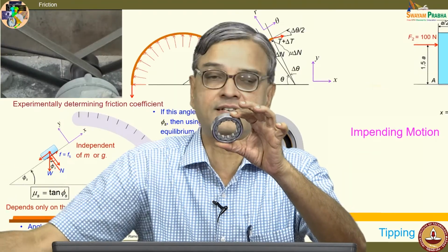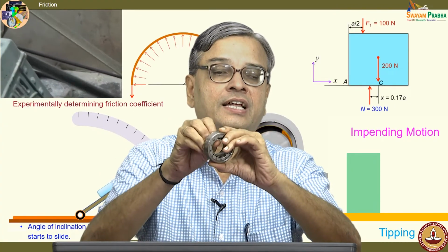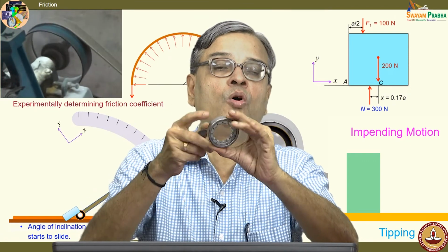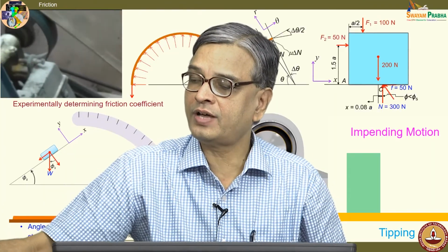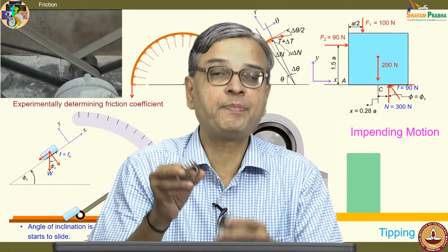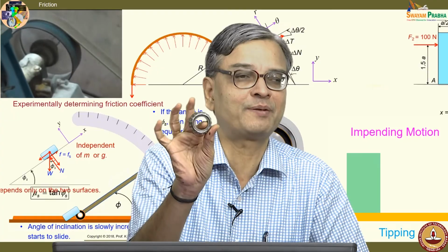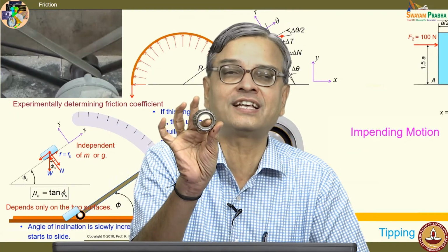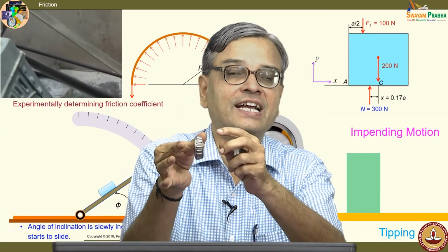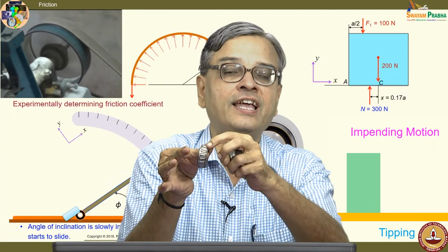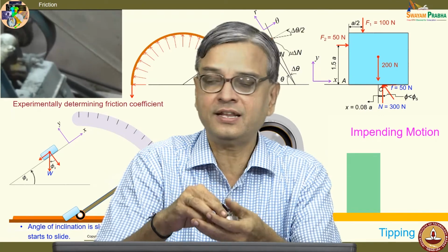Okay, the inner race is taken out. There is an inner race and there is an outer race. So, this will take more radial load than a simple spherical ball, and you also have tapered ball bearings. You look at the kind of complexity engineering has developed into. Once they have recognized that rolling has the least friction, they have devised various gadgets, and in this, you find it can take both axial and normal load. The tapered ball bearings are there.